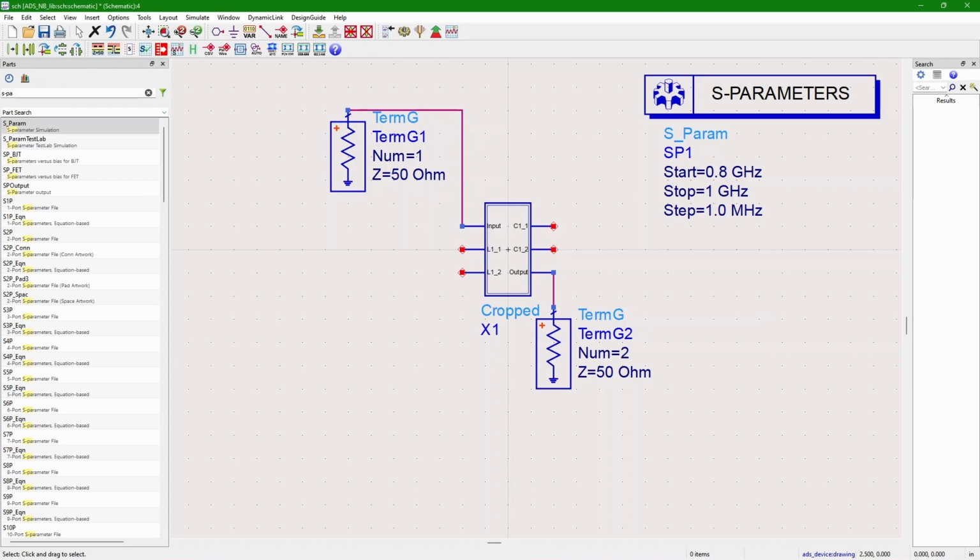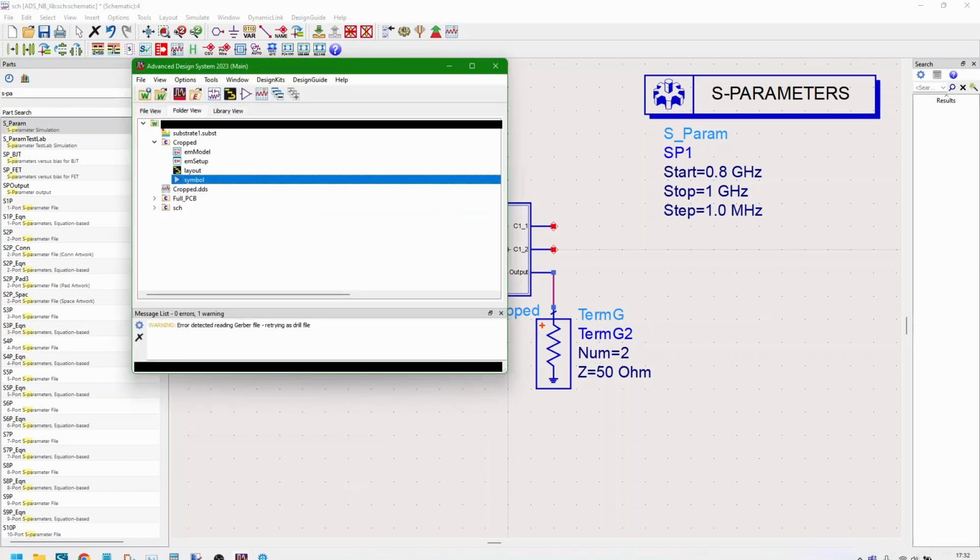We want to simulate this using real components, or at least the model for real components, not super ideal components. So what you're gonna do is download some manufacturer's database. They release these specifically for ADS. I'm using Murata components here, so I'm gonna use the Murata library. So download the zip file the manufacturer made available. Open the main window here.